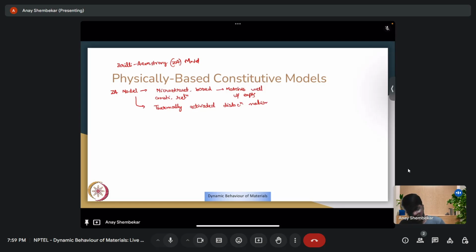So as we mentioned, you have the different forms for strains and strain rates for the L star. And Zerilli and Armstrong also observed that BCC metals show higher sensitivity to both temperature and strain rate than FCC metals.